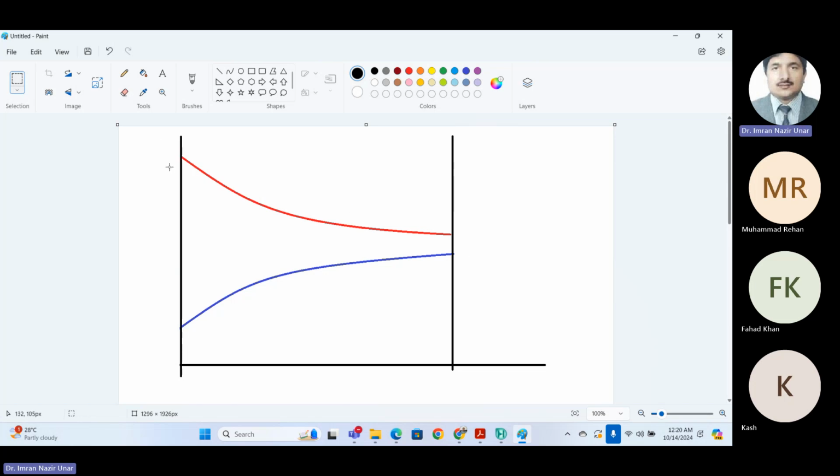The left side is the inlet and this is the outlet. So on the left side this is your delta T at inlet. For example, this is 80 degrees centigrade and this is 25 degrees centigrade. You may find some difference in the outlet streams, which is called the approach of the heat exchanger. This is a normal thing.